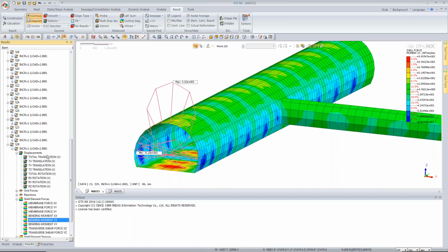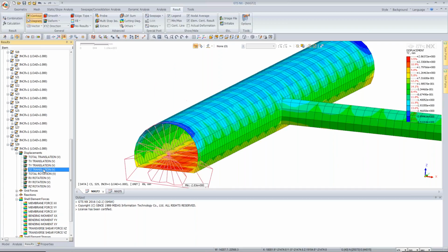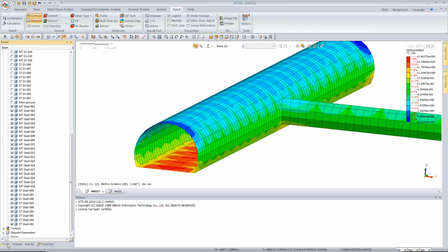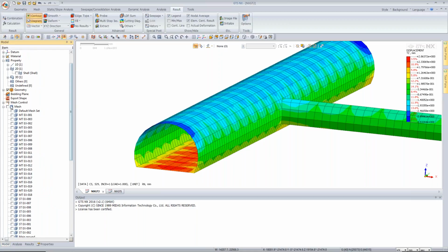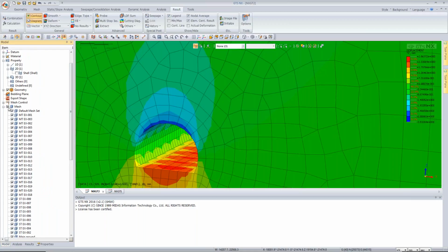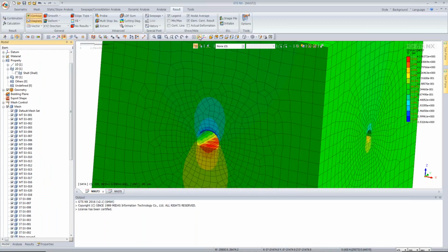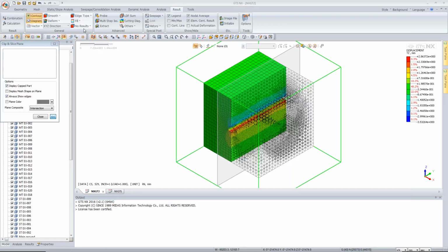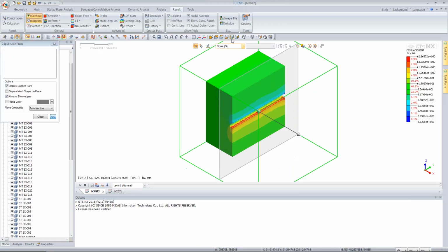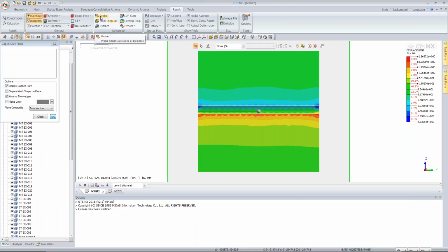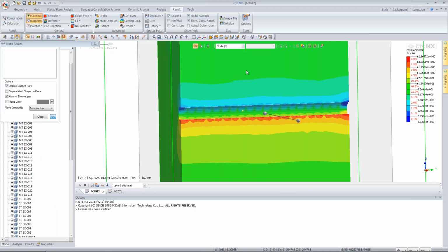Then you have now a very big problem that comes when we say TZ. Okay, now let's just hide this cutting line diagram, and I'm just switching on everything. Fine. Now, when we clip it, what happens is, let us make it no edge. What happens is at times you want to probe. What is the value here? Okay, but you cannot probe it because you don't know whether exactly there is a node or not, because you know that you can only probe at nodes.